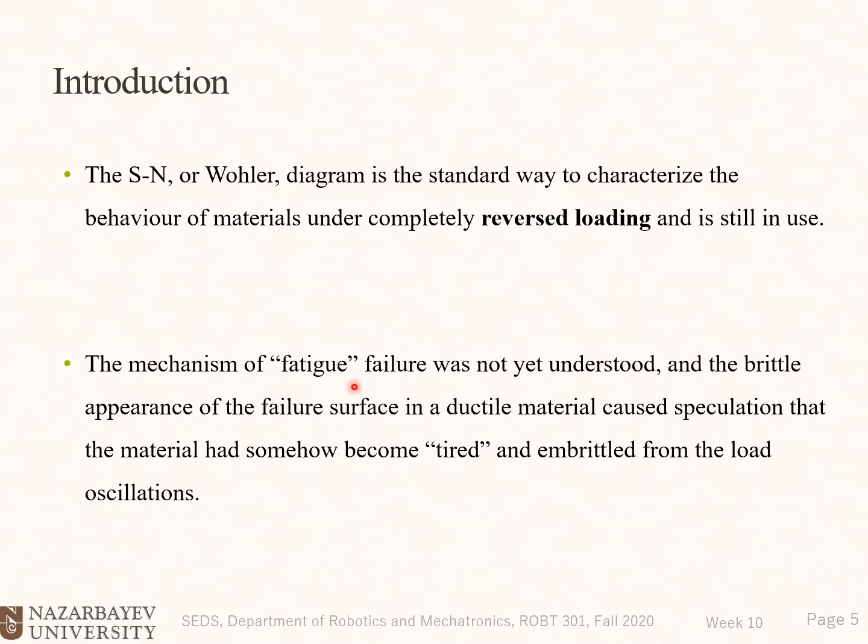The mechanism of failure in fatigue was not yet understood. So in the past, they didn't know exactly why the part fails under fatigue or under these dynamic loads and rotations. And the brittle appearance of the failure surface in a ductile material caused speculation that the part had somehow become tired and embrittled from the load oscillations.